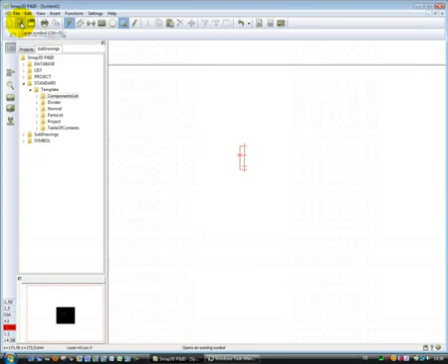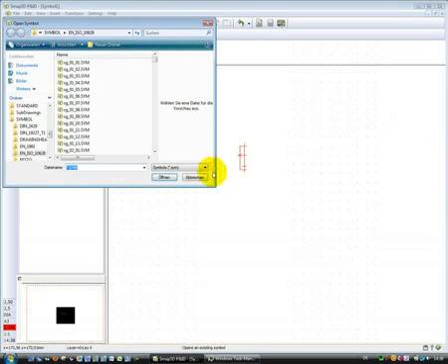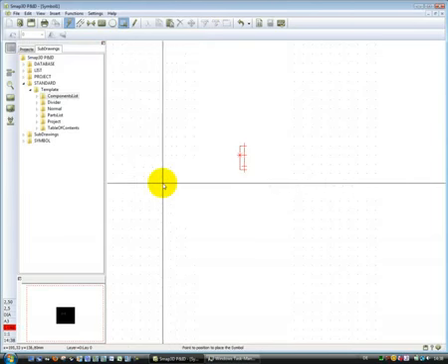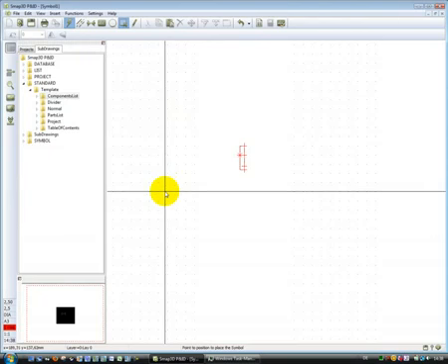Here I have the possibility to import DWG and DXF files with this external interface and use this geometry from blocks or from groups or from some other DXF or DWG geometry in my symbol, and with this I can use the external geometry as a symbol here in my software.